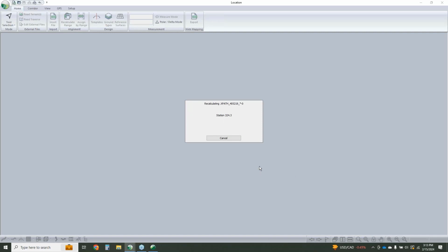There was a great question in the chat just asking, how do we know which was the best route from the Path Explorer options? So you'll notice here at the end of the XPath name that's currently shown on the screen, that is actually just like the rough cost that's being calculated. So when you go to look at the different Path Explorer options, looking at the name, the numbering, I should say, in the actual feature name will help to identify which is cost-wise the best route. I hope that answered your question.